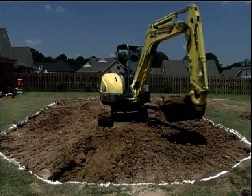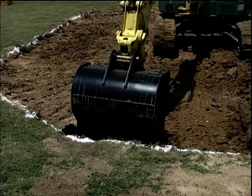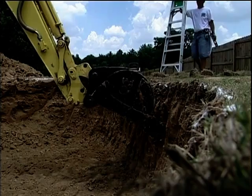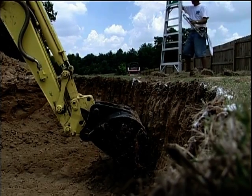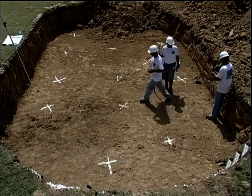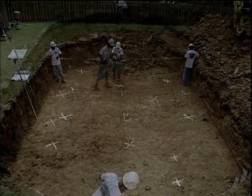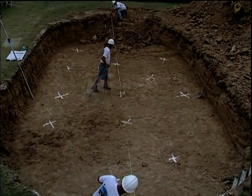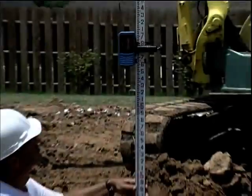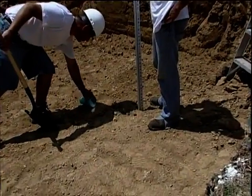As the excavator begins the digging, be sure that he does not dig outside of the marked area. Use a level on the sides to make sure that the digging is straight down and does not drift. The sides of the excavated area must be straight down. When the desired depth has been excavated, the pool outline must be staked again, but in much greater detail. Reference pool layout dimensions from your assembly guide. Constant measuring during the excavation process guarantees the accuracy of the proper pool depth.